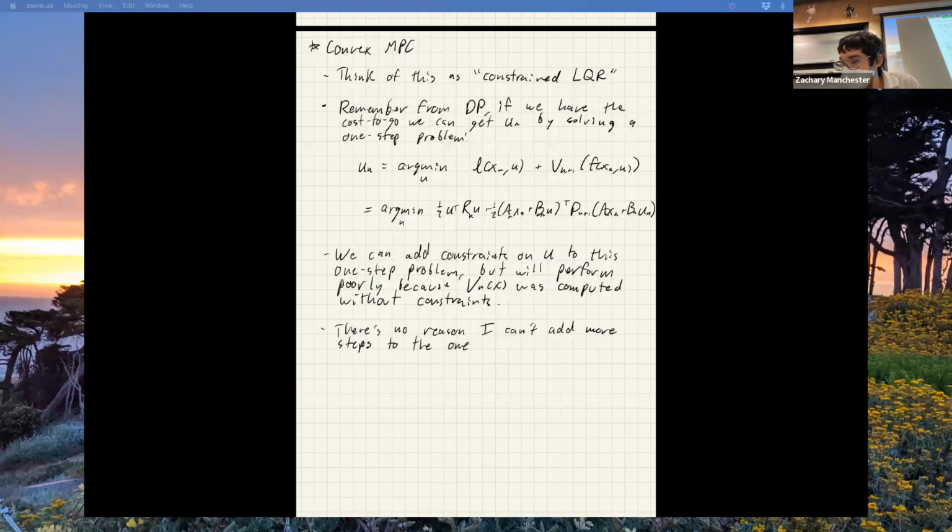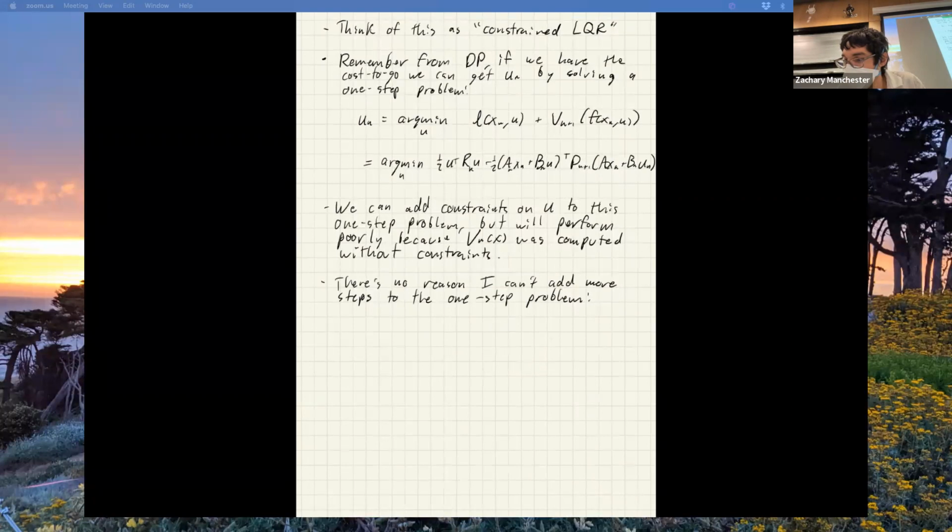So here's the setup. It's going to look almost like the standard LQR problem. I'm going to have min over x, 1 to H, and u, 1 to H minus 1. So H instead of N is basically the only difference, and everything else in here is going to look like standard LQR.